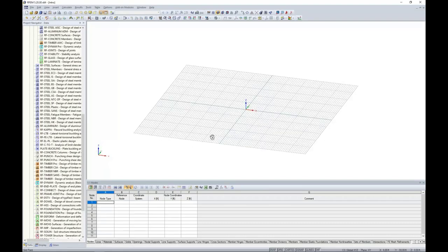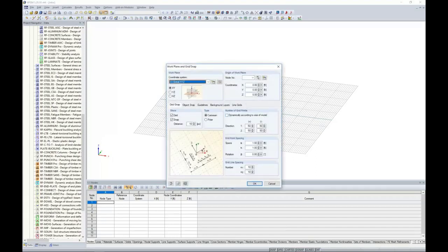So to begin today, I want to right-click down at the bottom of the screen under Grid. I want to edit the grid, and right now the default spacing is set to 1 foot, which is entirely okay. You can increase that or decrease that. I do want to increase the number of grid points on either side of the origin and set this at 100 because our structure is fairly big today.